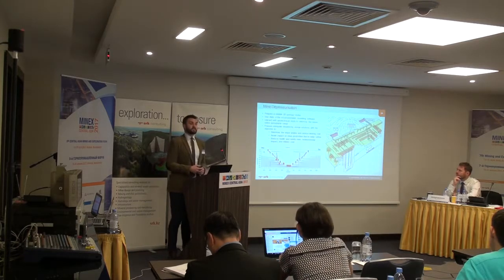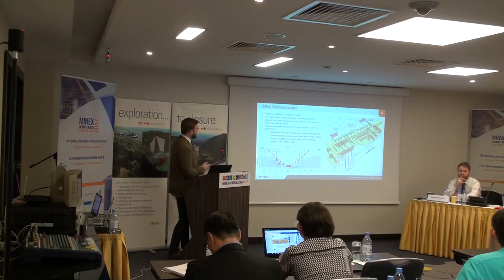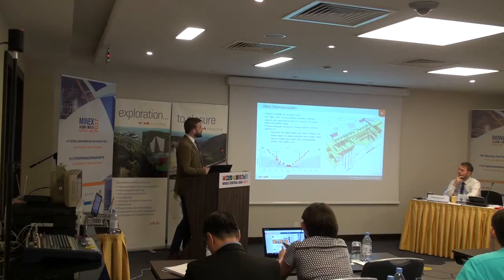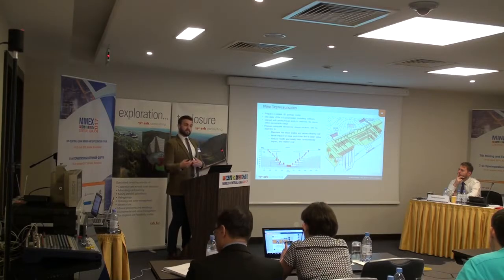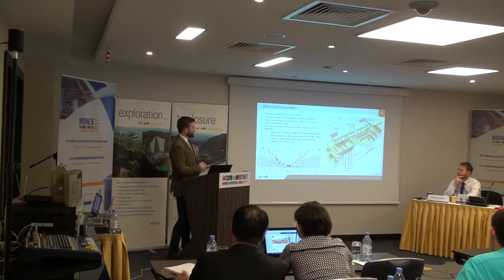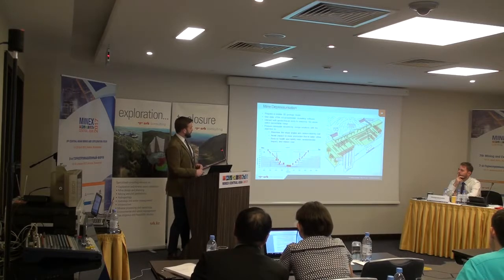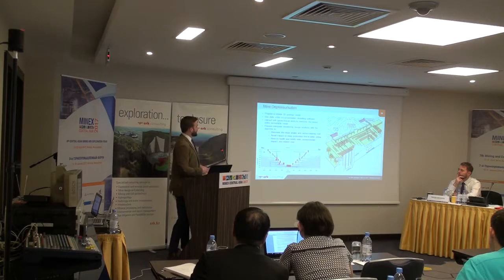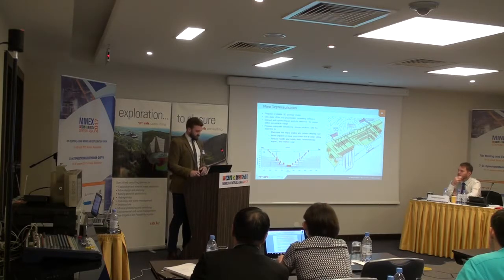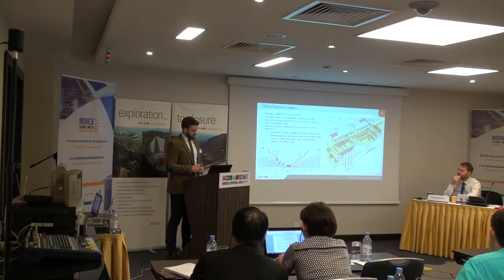And if it warrants it, mine depressurization could be used to try and reduce the amount of groundwater pressure, or the effects of groundwater pressure, on the slope, and that will then maximise your slope angles and reduce stripping costs. Avoid impact on the mine production due to water inflow and reduce health and safety risks, environmental impact and related costs.